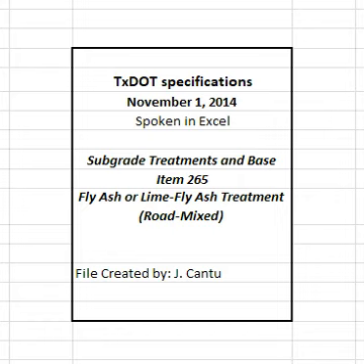Do not surface patch. 4.7 Curing. Cure by maintaining in a thorough and continuously moist condition by sprinkling in accordance with Item 204, Sprinkling. When permitted, cure with an asphalt material applied at a rate of 0.05 to 0.20 gallons per square yard as approved. Do not allow equipment on the finished course during curing except as required for sprinkling, unless otherwise approved.